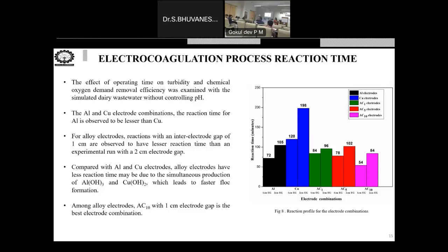And the uniformity of the alloy is determined by a process called stir casting. When the entire subject is in molten state, we have a stirrer above it, and we provide some mixing. We can't keep it open, it's very high temperature, so some agitator, insulated, goes inside and provides mixing so that the entire liquid will be homogeneous, somewhat ideal. Then only we pour it to the mould. So first you are just melting them, then stirring to make a homogeneous mixture, then only it will be taken to the casting. Okay. Any other doubt?